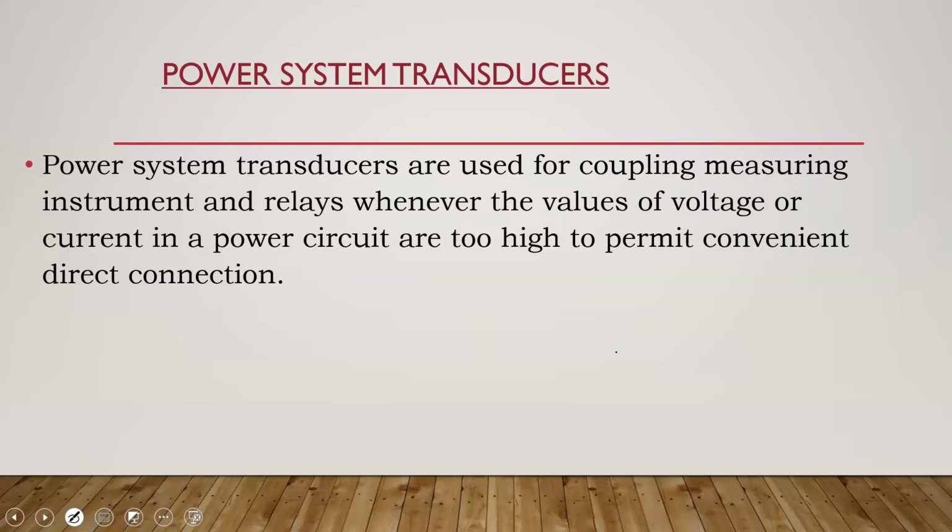So for your CT, you're usually going to be using a CT when you have currents above 200 amperes. So when you start dealing with currents in that region, 200 and above, you start thinking about CTs.